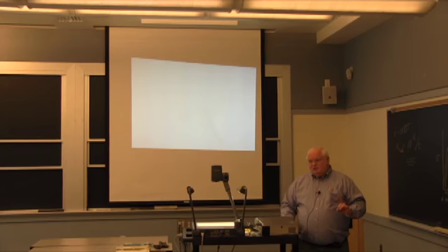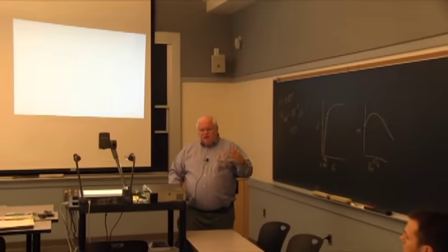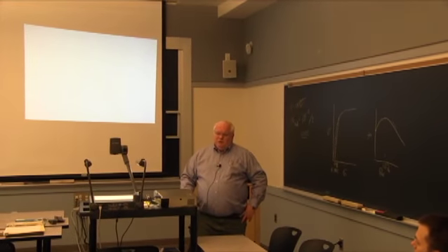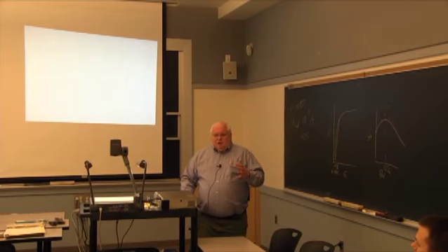And the strain tensor, well, there are 9 values of strain and 9 values of stress. And the tensor that matches the two has 81 coefficients, right? Now you can prove that only, I can't remember, anybody remember, it's 31 or something are independent, because there's some symmetry to this. And if you assume that there's no volume change, you can get it down by another 1 or 2. But you still end up with all these things.